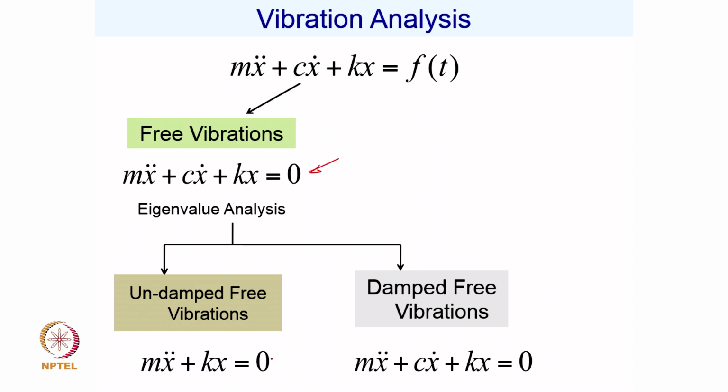Now, the first step of this undamped free vibration most of the times is to assess the natural frequencies, and the equation here is a classical eigenvalue analysis equation.